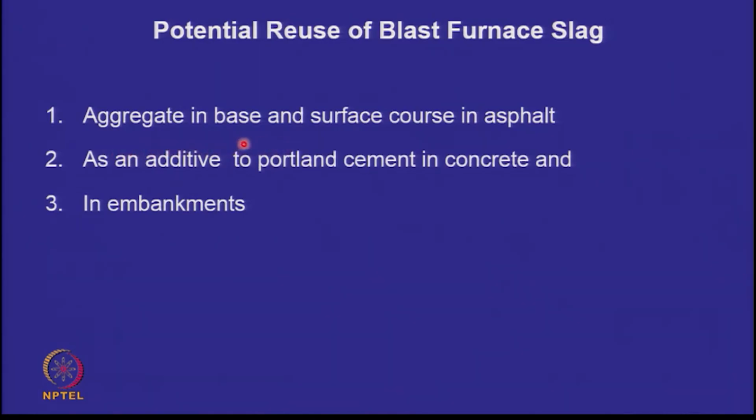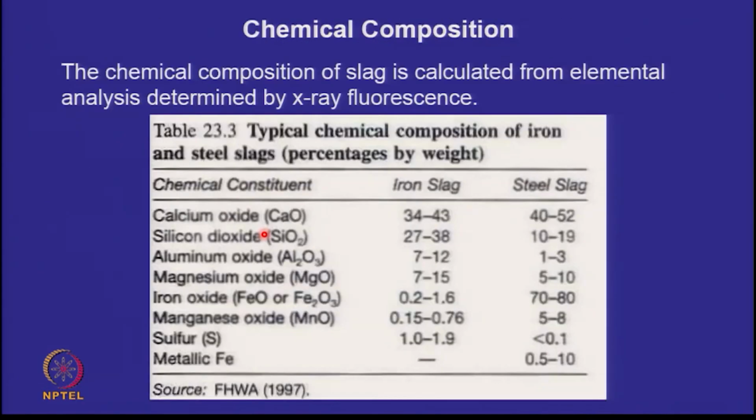So it has been used as an aggregate in base and surface courses in asphalt pavements. The slag has also been used as an additive to Portland cement in concrete, and slag has also been used in embankments. So let's try and unravel what slag is. And this is the data which I picked up.